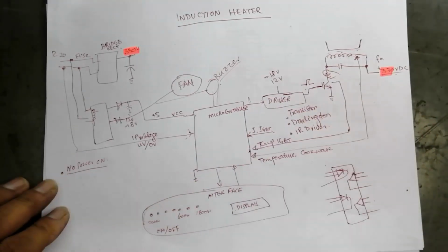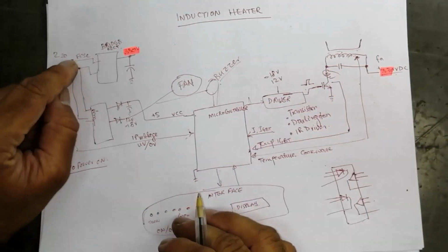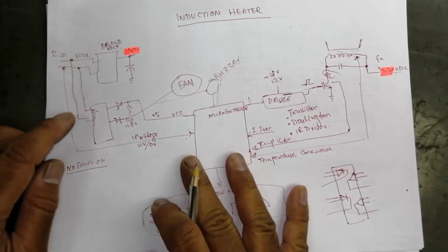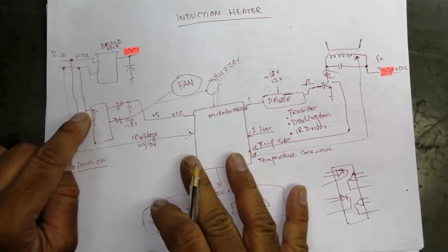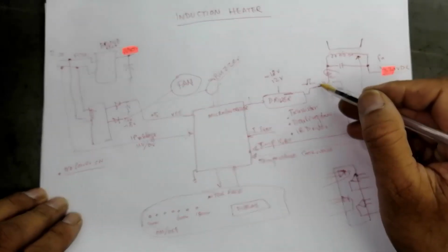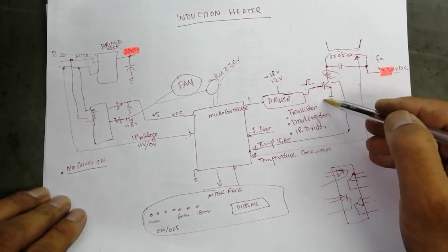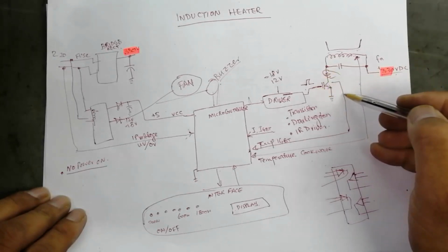Check the fuse, basic. Then you have to check this power supply. Sometimes we have a short circuit in the IGBT. Most of the time there is a problem in the IGBT.